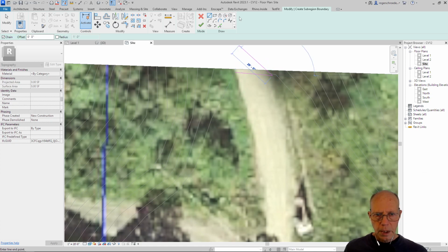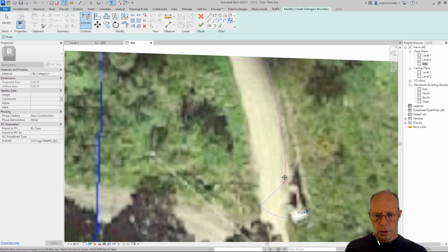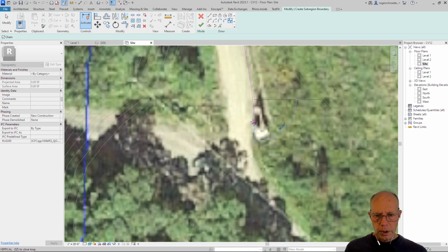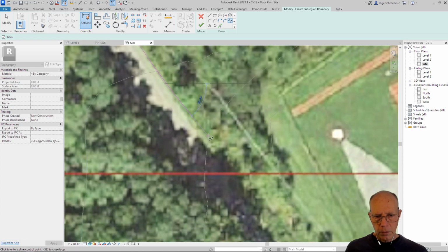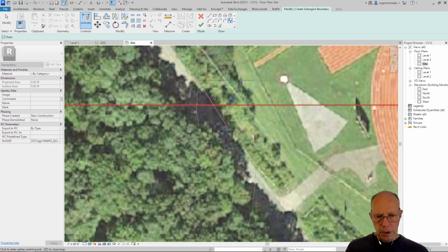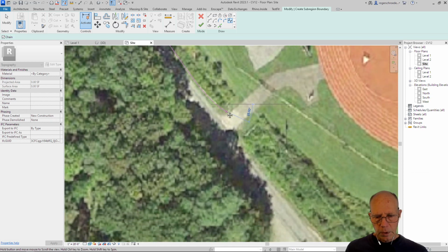So I'm going to select that, and now I'm just going to change my tool to a spline tool, and that'll allow me to make these kind of curved surfaces as we move along and follow the contour of the road. So I'm just kind of touching the edge of the grass here, and where curves change sharply, you want your points to be really close together, and where they just change gently, you can spread them out further apart. And at some point, it's so tree covered here, you'd really just have to make some bit of an approximation.